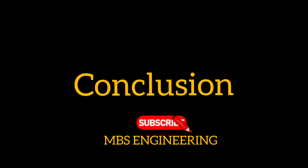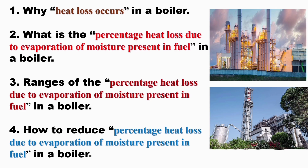Next, let's recap what we've learned. We understand why heat loss occurs in a boiler, and the heat loss due to fuel moisture is a major efficiency issue. Next, it varies significantly by fuel type. Next, it can be reduced effectively through drying, storage, control systems, and combustion optimization.